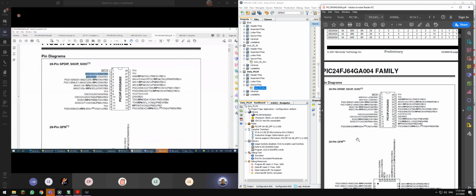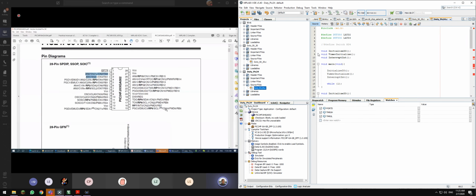Okay, so let's come back. Let's say we are using the same line. We always go towards the end, RB6 and RB7, or up to you. You see, why I choose 6 and 7 is because they don't have an analog pin. So be careful when there is sharing of analog pins. You have to ensure that these 2 pins are set to become digital pins and not analog pins. By default, it's an analog pin. Remember this.